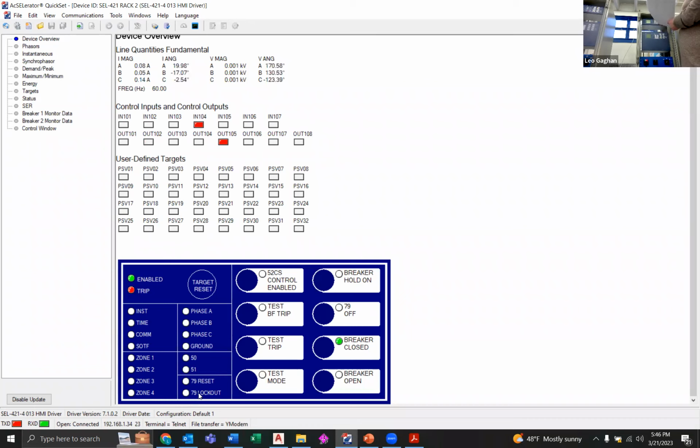And then last one, we tripped and we drove to lockout. We can no longer go through the reclosing cycle. So that's a full sequence. If I would have not given it a test trip maybe after 2 cycles, it would have just, you know, kept on going. It would have restored the line automatically, and things would have been great. So that's working through the test cycle.